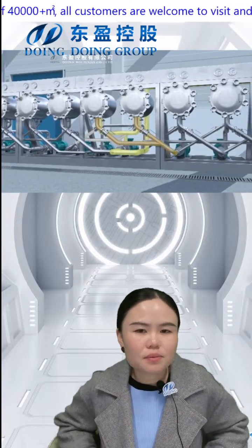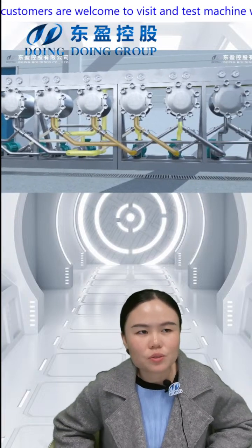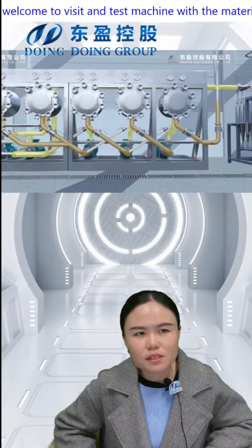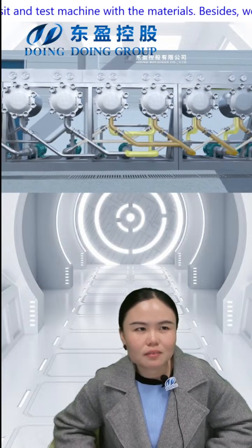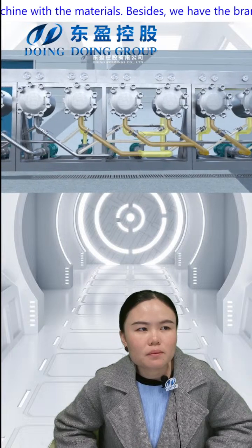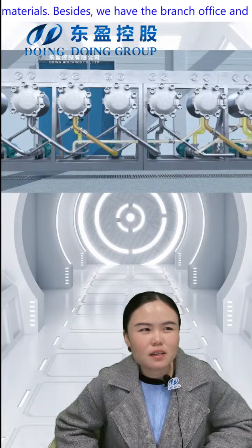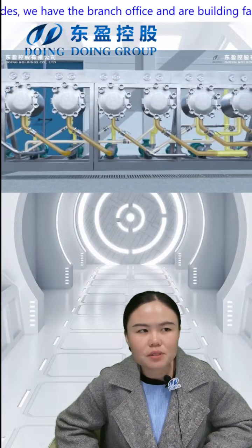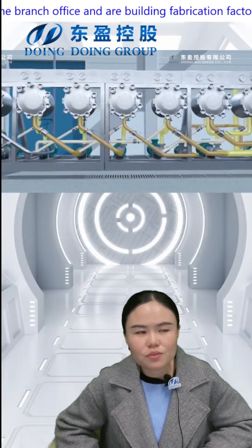One stage of separation cannot separate completely, so to ensure the separation efficiency, we will use multiple stages, 18 stages, so that the cyclone machine can ensure the starch quality, and at the same time recycle the starch and reduce the starch loss.